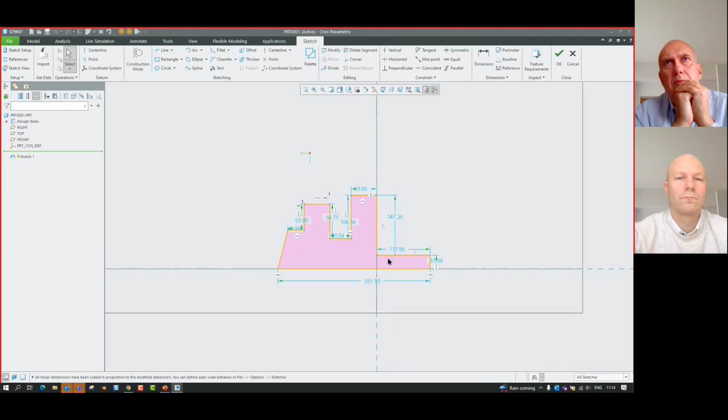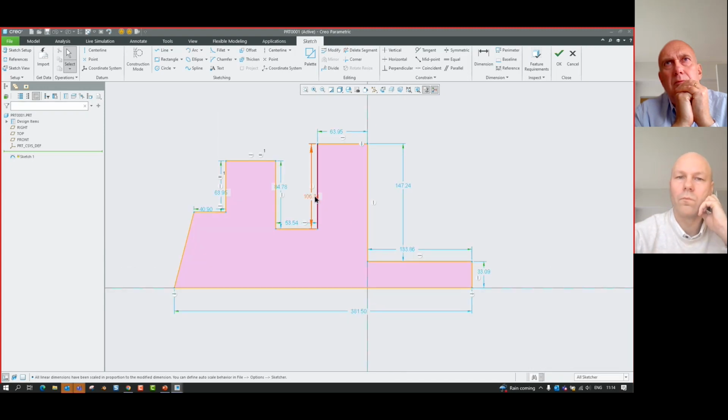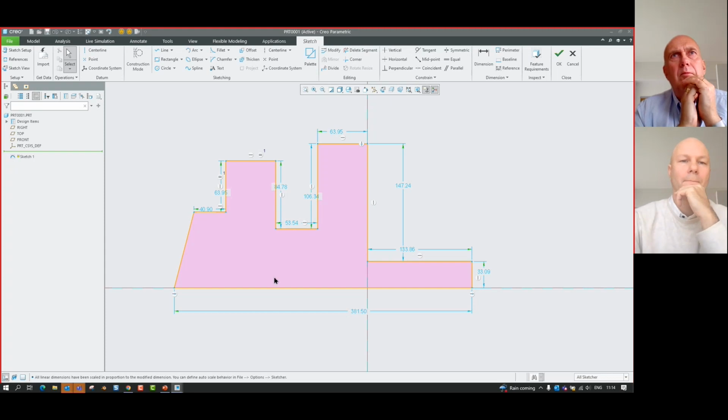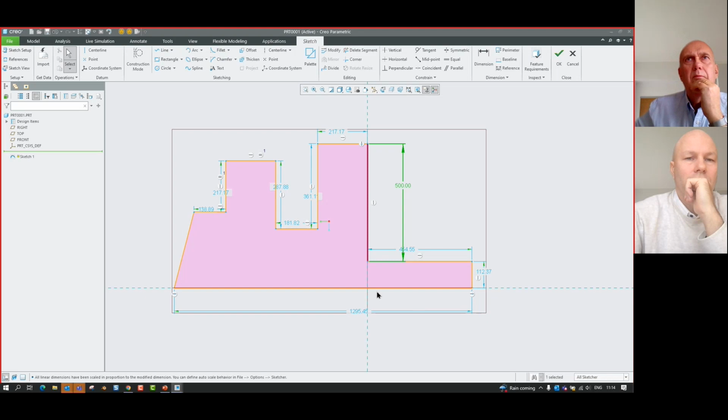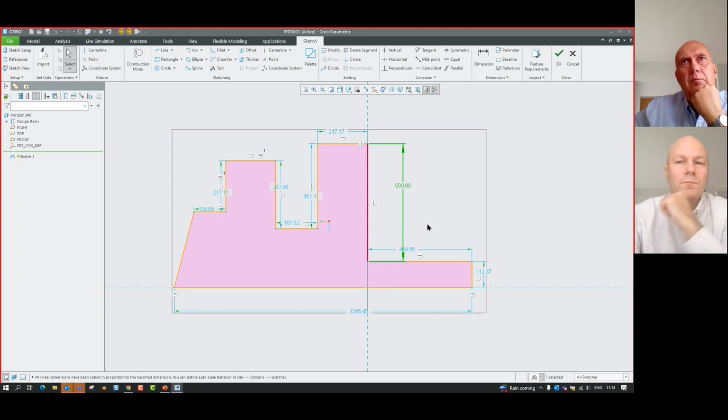So I'm going to undo that change and let's pay close attention to all of these dimensions and take a look at what happens. Once again, I'll change this to 500 millimeters and you can see that all of these corresponding dimensions here have automatically scaled up by the exact amount that I've scaled this initial dimension by, allowing us to preserve the geometry of this sketch. So that's Autoscale Sketch in Creo 9.